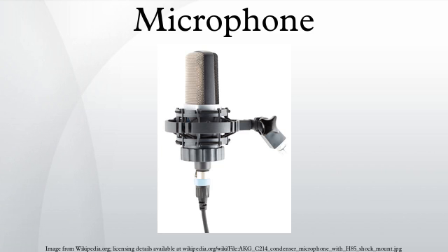These repeaters worked by mechanically coupling a magnetic telephone receiver to a carbon microphone. The faint signal from the receiver was transferred to the microphone, with a resulting stronger electrical signal to send down the line. One illustration of this amplifier effect was the oscillation caused by feedback, resulting in an audible squeal from the old candlestick telephone if its earphone was placed near the carbon microphone.